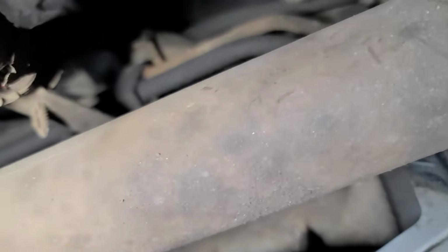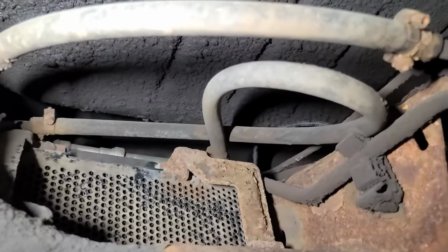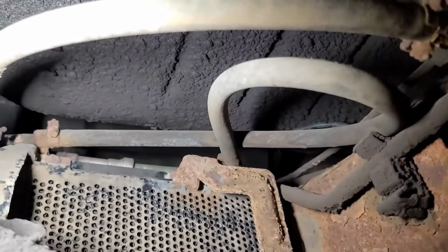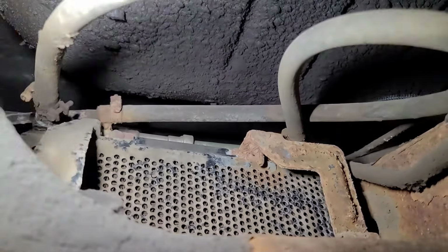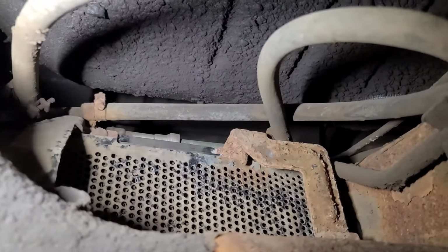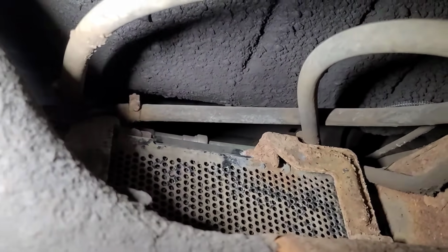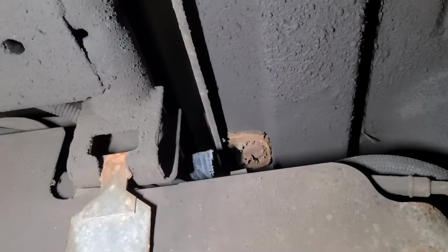The lines don't look too bad unless it's compromised above the tank. And I lent my borescope to somebody, so I can't look up there. Now, that coupler up there that you see right there, if I could disconnect that and put a piece of clear hose in between and reconnect the lines up top and start it up and watch for bubbles, I would expect that once it's running, it would stay running. Unless there's no fuel in the tank.